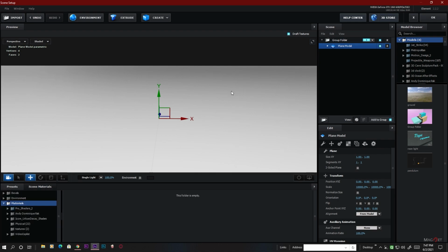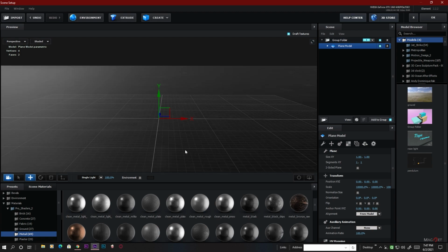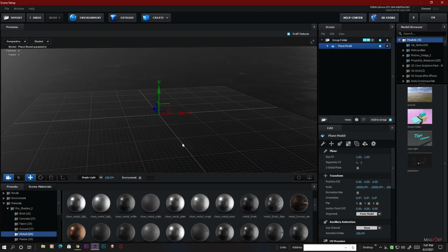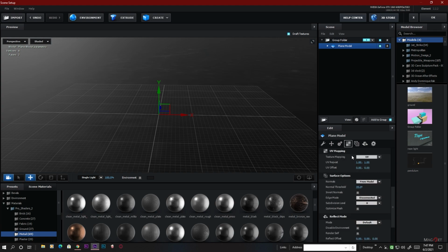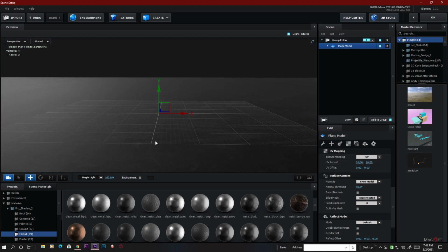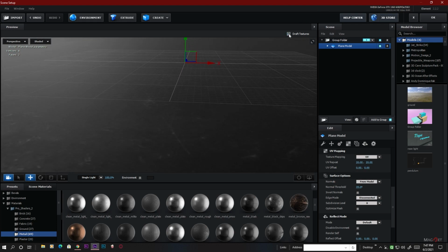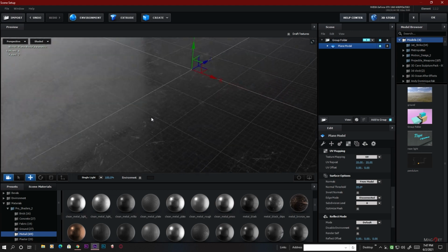Now we are going to apply some metal texture that I use from the Pro Shaders from VIDEOCOPILOT, and maybe we need a reflective texture here. So go to the metal here and maybe we use this one. This looks very reflective, and now we go to its UV map settings here and increase the repeat value to maybe 10 by 10, or maybe you can increase it to 20 by 20 if you think so. Now it looks very high res and crispy. If we disable this drops texture value, you will see this looks very high res.